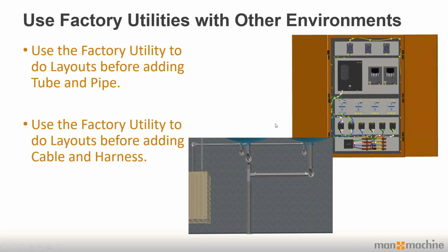And of course, if we publish tube and pipe components, publishing assets with nozzles and nozzle connections can definitely help when we're laying out general assets within something like a water treatment plant, which I'll be showing you shortly as well. We can then just go and add our tube and pipe connections to those assets and simply work from there. So it does work very well when adding it to the other environments that we have.